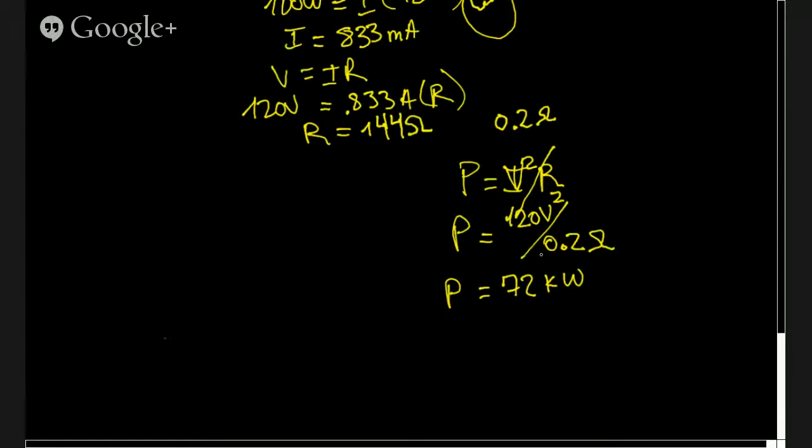And because there's only so much wiring in your house, which is a certain gauge of a certain cross-sectional area, if we have that big of a load, we have our small resistances in our wiring, or the resistance from being a thin gauge wire.